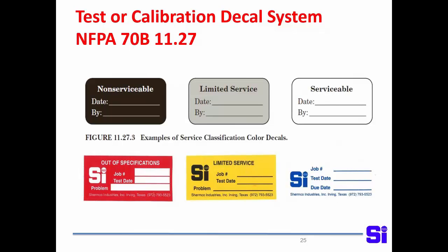So as I move away from that test date and I get closer to that 3-year test interval, the likelihood of that equipment working in accordance with the manufacturer specification starts to become less. How much less? Can't tell. But I know that if I'm at the 3-year mark or close to that 3-year mark, I want to be a little more cautious around that equipment. So it still gives me a lot of information that I need.